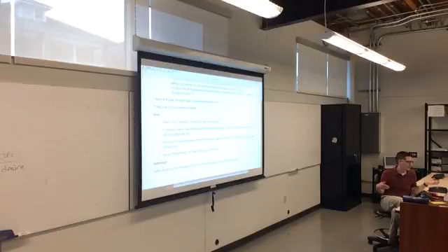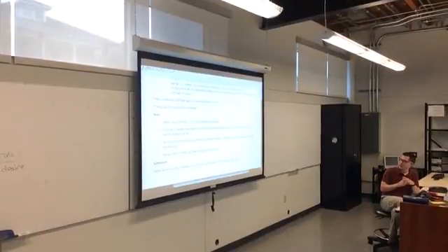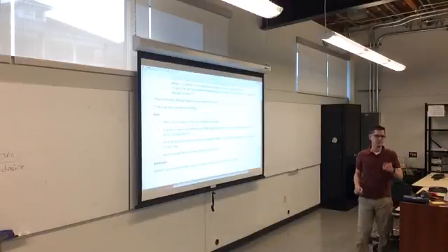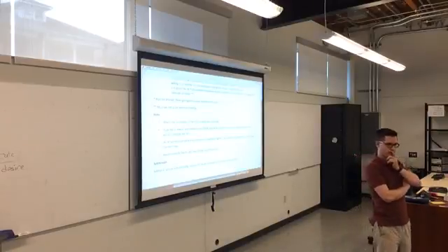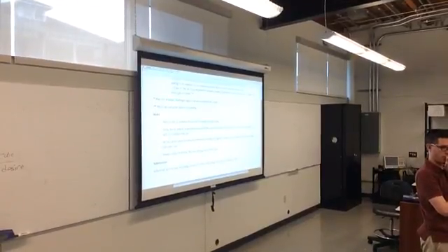Yeah. Travis, yeah. The select line should be, right, you don't have the chip select line on this board. You do not have to do anything with it. The SCL is the I2C clock line. Yes, that needs to be the wired-AND output, correct?